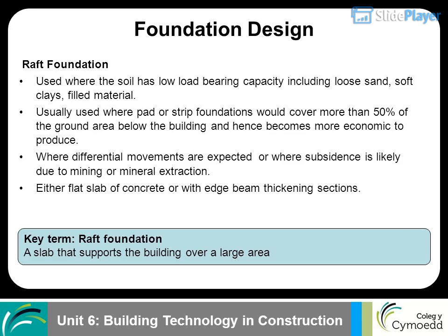Foundation design: raft foundation. Used where the soil has low load bearing capacity, including loose sand, soft clays, filled material. Usually used where pad or strip foundations would cover more than 50% of the ground area below the building and hence it becomes more economic to produce.